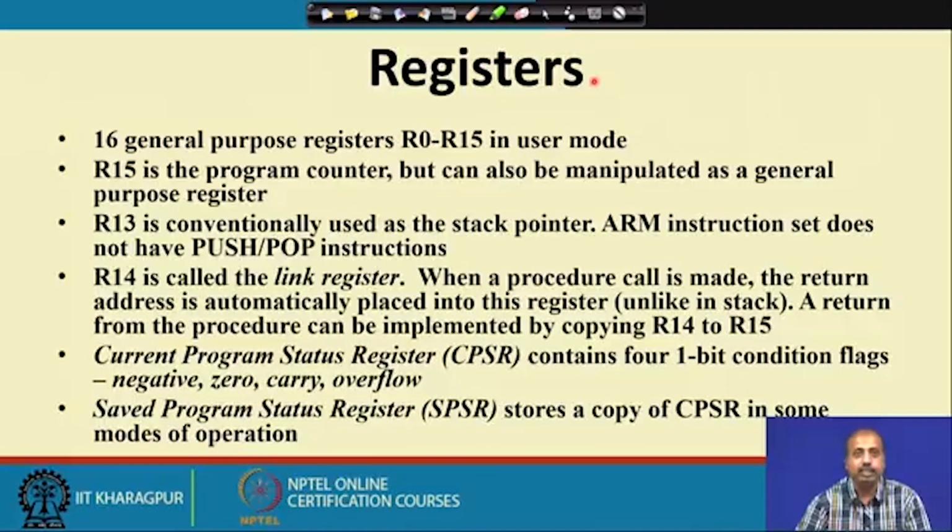Then the R13 register is conventionally used as stack pointer. Please note the term conventionally. It means that there is no hard and fast rule that I have to use R13 as the stack pointer. I can use R13 as a simple general purpose register also, but in general it is used as stack pointer. Another thing to note is that the ARM instruction set does not have push pop instructions.